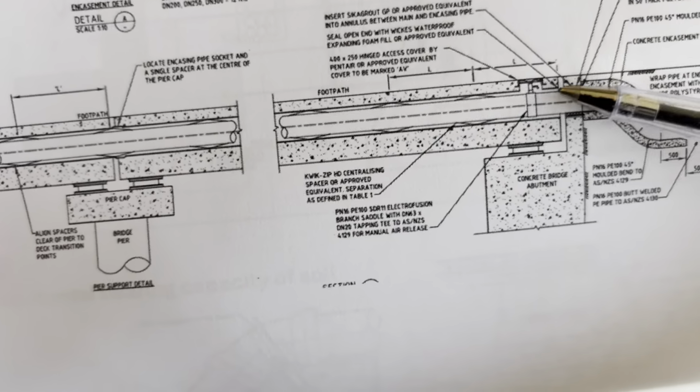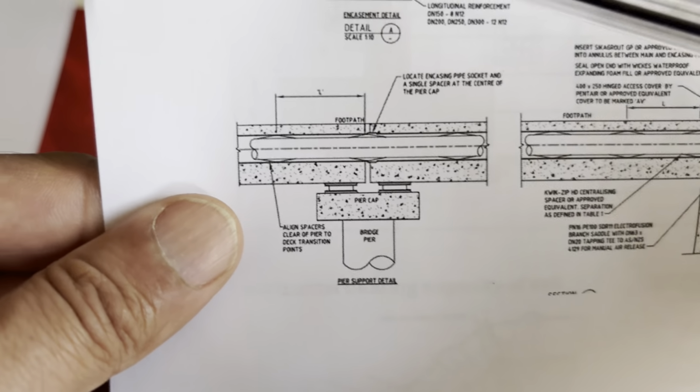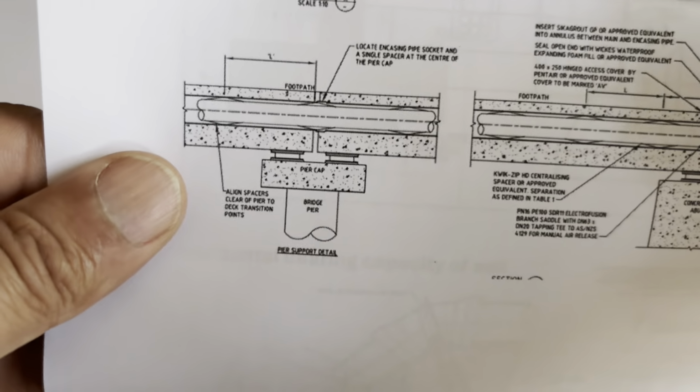It should be just like against uplifting pressure, and also the body, or the skin, of this concrete encasement should be strong enough for ultimate design. So we're going to provide some reinforcement for any shear or bending that happens on the skin of this encasement.